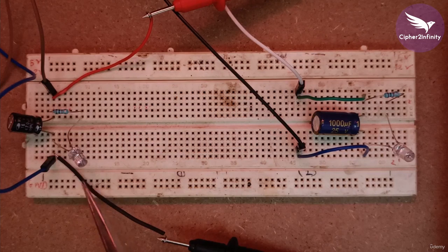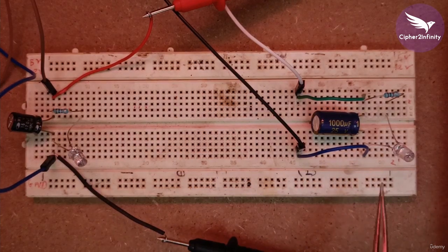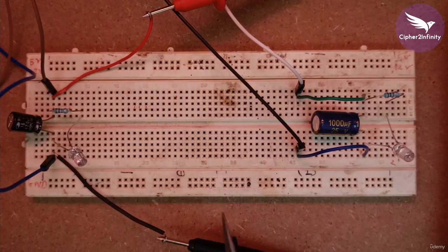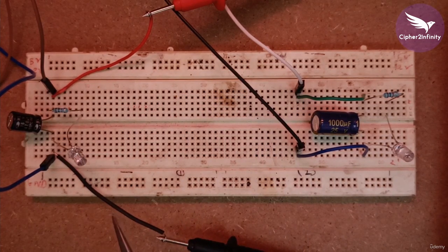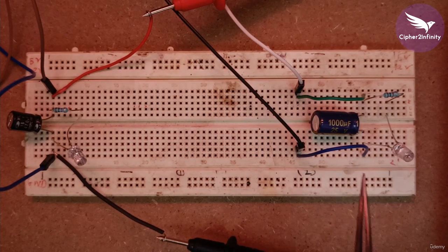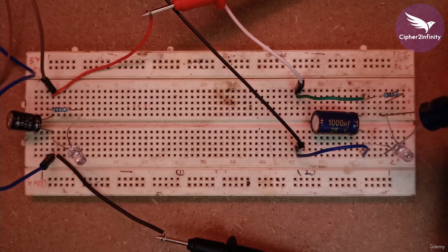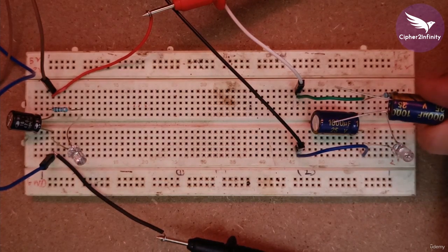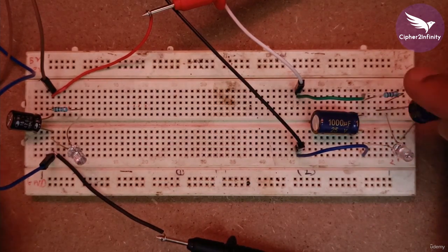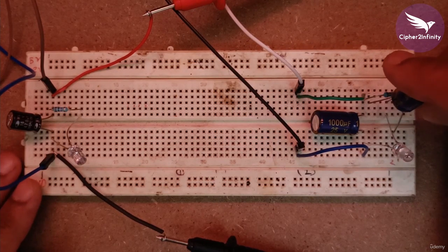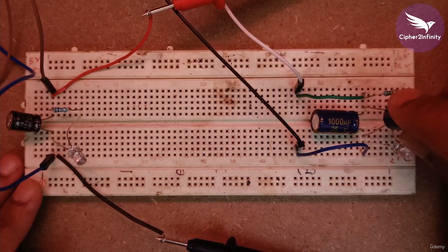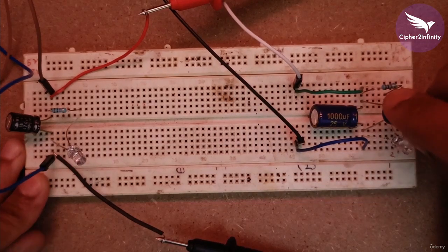You can see this LED switched off first, and later this LED switched off. That's the demonstration for the energy storage of a capacitor. Based on the capacitance, it is decided how much energy that particular capacitor is going to store. Now I will increase the capacitance at this point. I'm going to connect one more 1000 microfarad capacitor, in parallel to this 1000 microfarad capacitor. I will quickly do that.